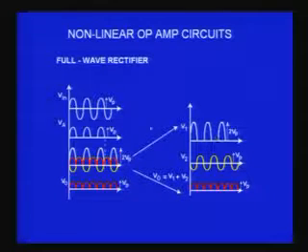Now when I give it to the summing amplifier, the summing amplifier amplifies the signal to twice, as I already said, and therefore it becomes 2 V peak. This signal becomes 2 Vp as a peak voltage, and the other signal is the input signal which is coming to the summing amplifier, and for that the gain is 1, and therefore the same signal is also there.